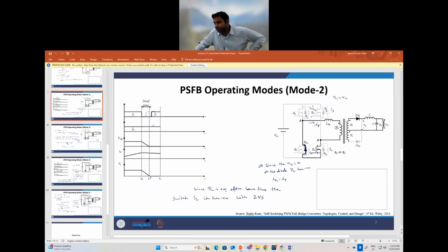You got my point? It is now like a two winding transformer. In a two winding transformer, you have the leakage of one side, then the secondary side leakage or whatever impedance you have, and you reflect it on the primary side. That's why we have to take it on the primary side. I don't understand exactly what the doubt is.